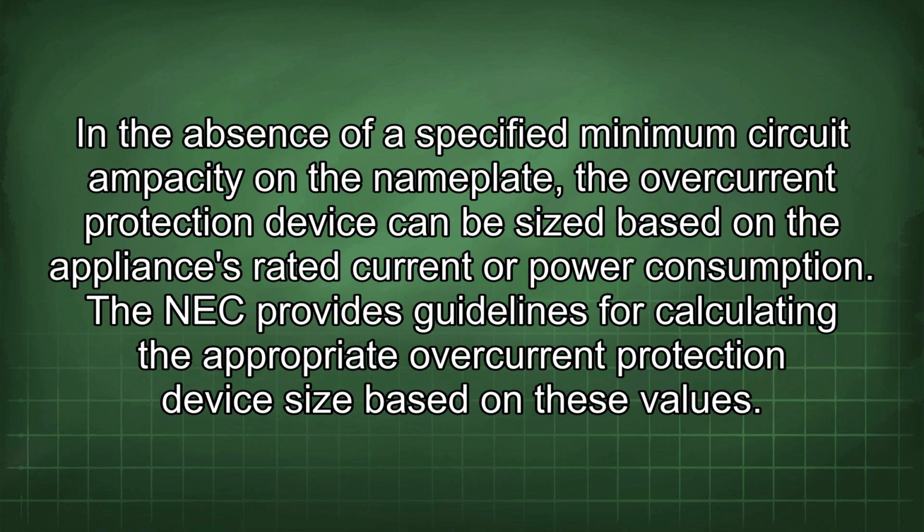In the absence of specified minimum circuit ampacity on the nameplate, the overcurrent protection device can be sized based on the appliance's rated current or power consumption. The NEC provides guidelines for calculating the appropriate overcurrent protection device size based on these values.